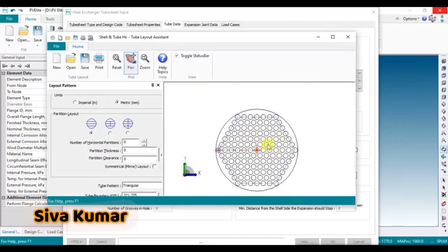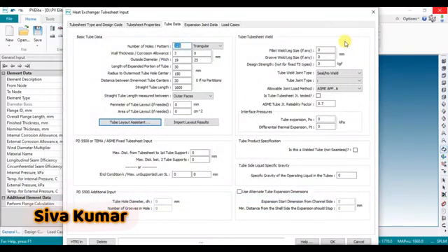So see. So then everything we have entered, and then here you see the tube joint type. There are many types there. We choose I type. Here there is seal and no weld. Okay. Then coming to this tube sheet, GT tested. No. Then weld leg size, if any, we can provide two mm.